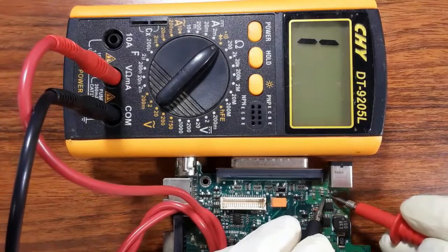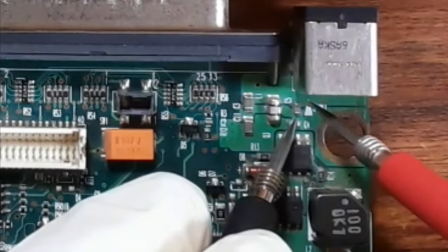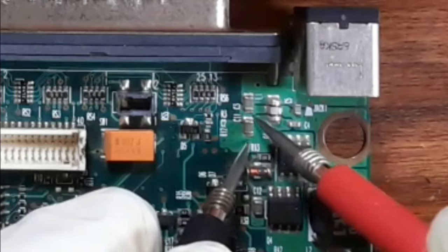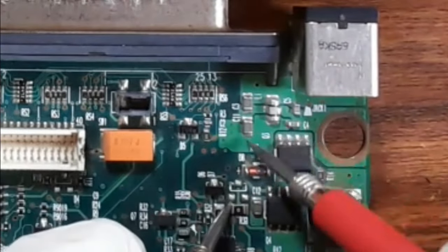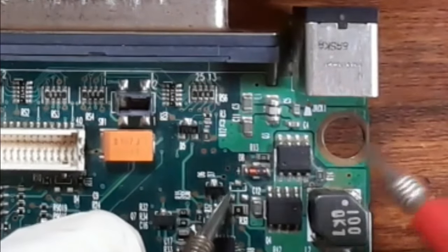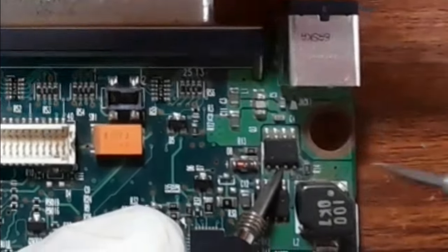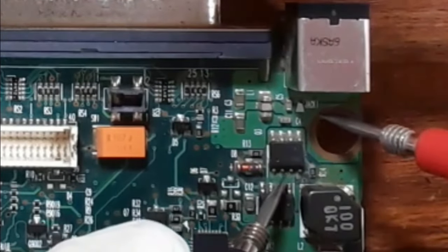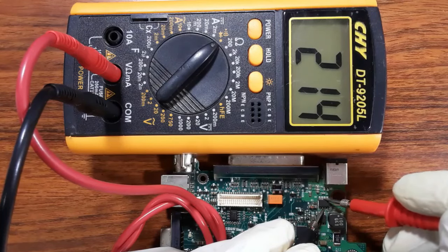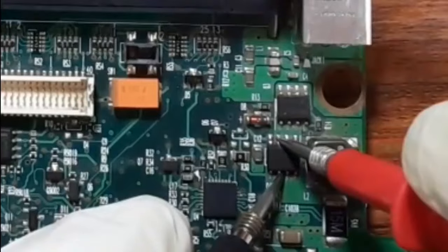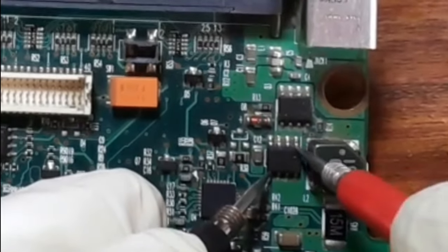Here we have some PF capacitor. For the PF capacitor, you should not hear any buzzer or any continuity. If you hear a buzzer or continuity, it means the PF capacitor is bad, or the IC near it is bad. Here we have a MOSFET, with source and drain. We can just check between drain and source. Continuity here means good. The same for this one.